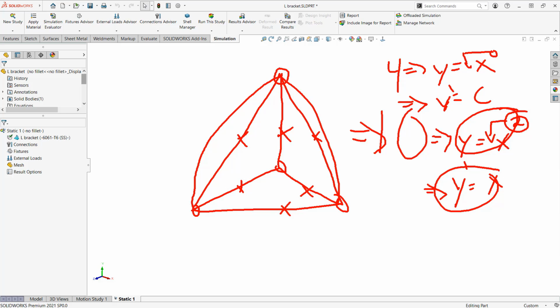Well, I'll tell you why. Because it's not free. Now, you have 3 degrees of freedom, x, y, z, in each node. So each equation is solved in each one of those degrees of freedom, x, y, z at each node. So you have 30 equations versus 12 equations up here, right? So a linear element has just 12 equations. So you've then more than doubled the amount of equations that are going on in your matrix. So that means it's going to take a lot longer to solve.